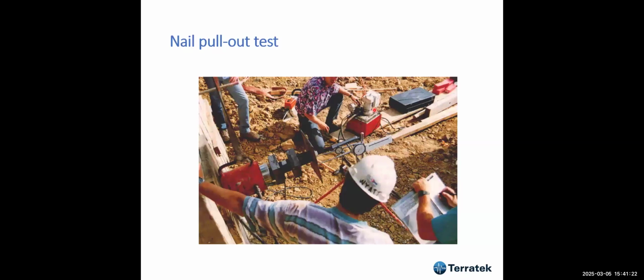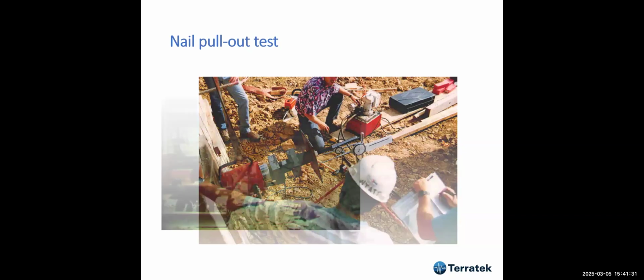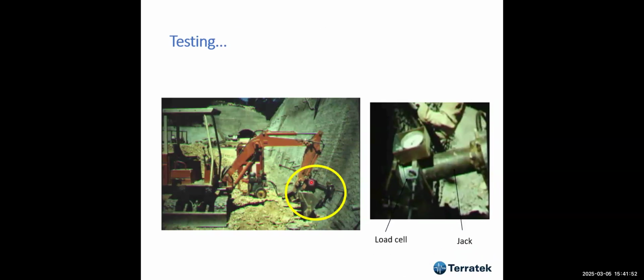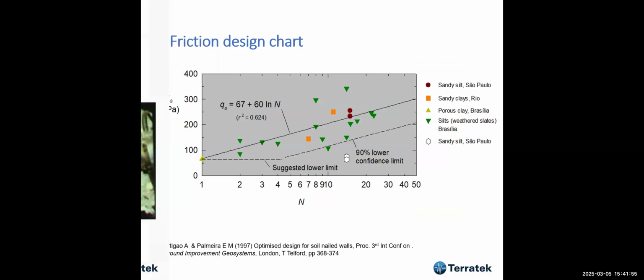And so, the nail pull-out test. This is a typical arrangement to carry out this kind of test. Very simple, as I've told you before. This is the French experience, in which they came up with a jack held by this hydraulic rig in order to make many tests very fast. They could move it alongside the work to do several tests, with a jack and a load cell.